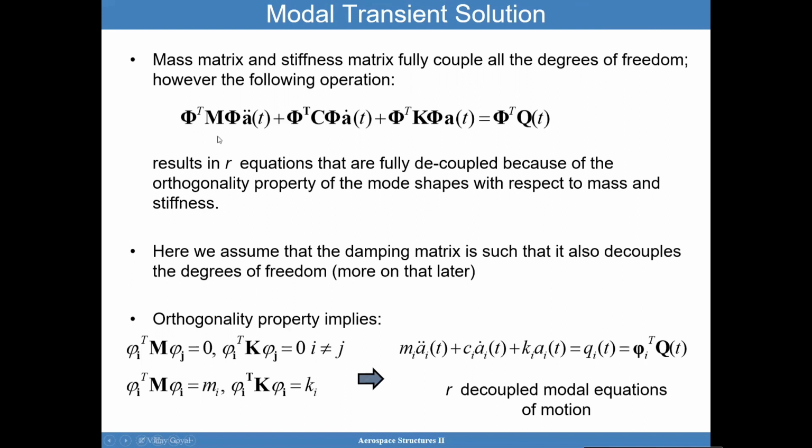The bottom line is when you perform this particular operation, not only did I have millions of degrees of freedom reduced to 7 or 30 equations, which is way better than millions of equations, but further, I have decoupled them into 7 equations. I turn a whole rocket into mass and spring stiffnesses that are decoupled, fully decoupled.